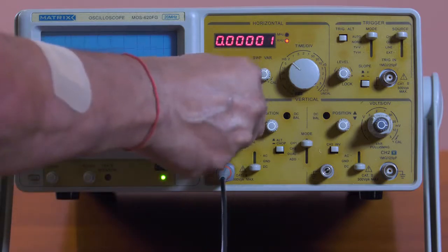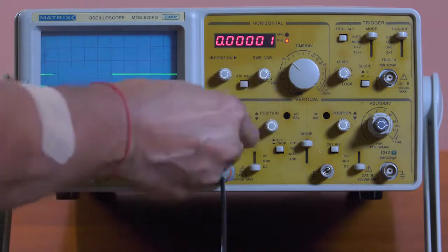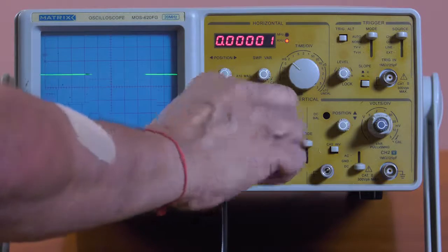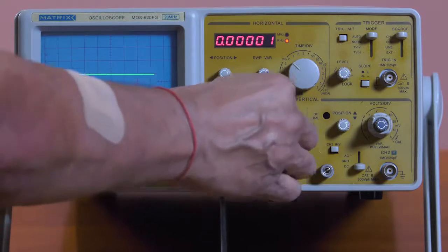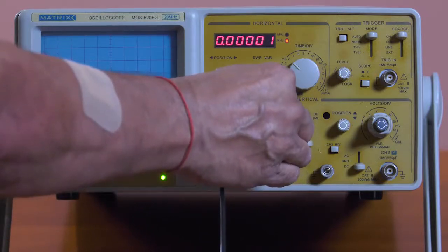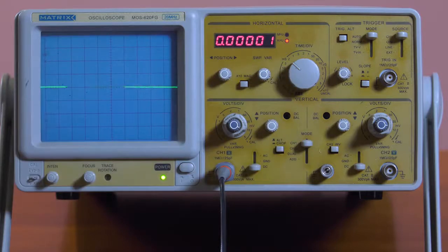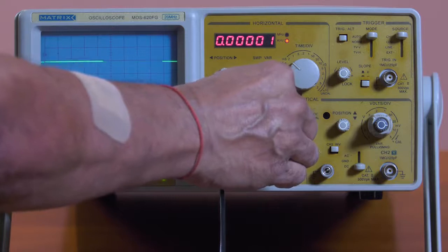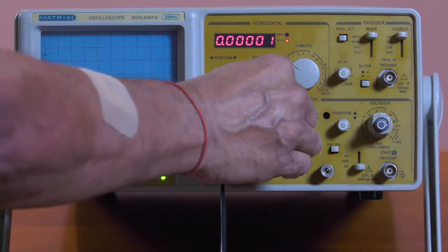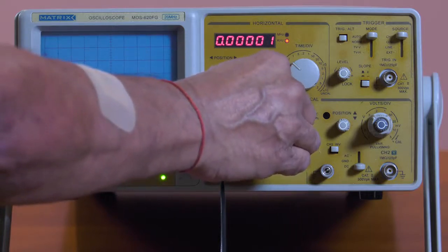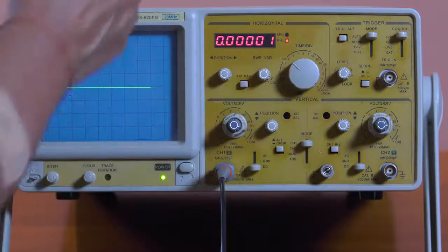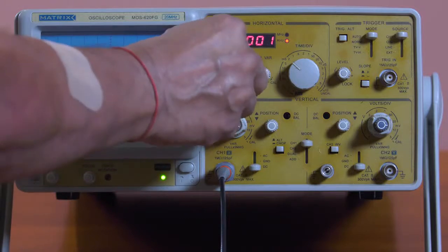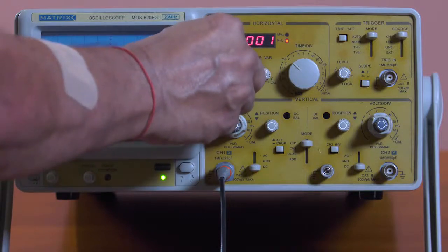So I'm going to centralize my trace. This is my position. You can see the arrows here telling you it's vertical. I like to bring my trace to the middle. I could actually make measurements with a trace there or there or there, but the point is, if I have quite a large voltage to measure, then the trace will disappear from the screen, and that's going to make it difficult for us to see anything. So we're just going to get this there like so.